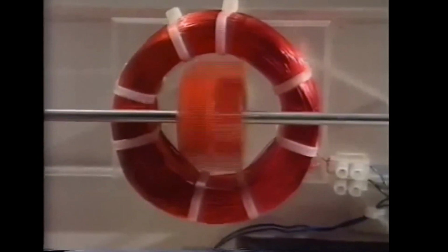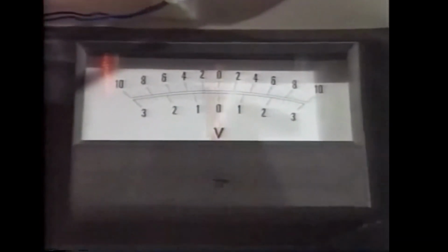This apparatus demonstrates the principle involved on a small scale. It's a miniature power station. The steam produced by boiling the kettle is directed at the turbine. It strikes the blades and makes the turbine rotate. The turbine drives the generator, a magnet moving in a coil of wire with many turns in it. An alternating current is generated. Notice the change in direction of the needle.